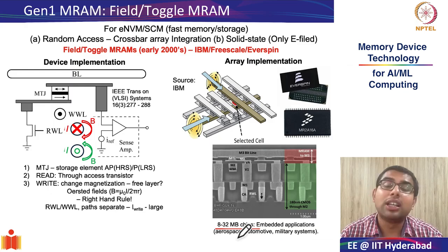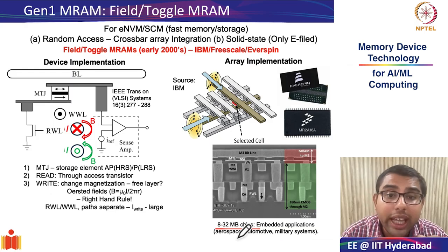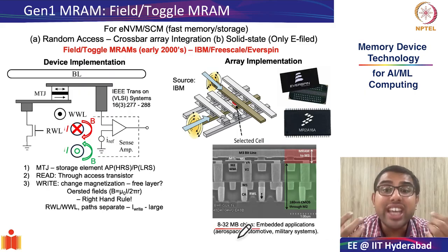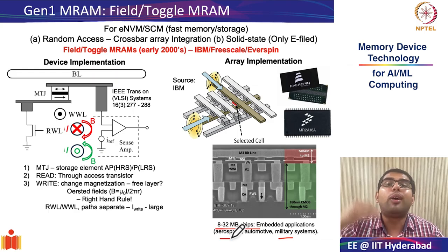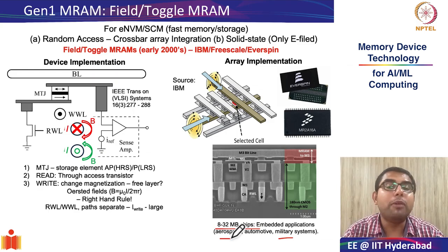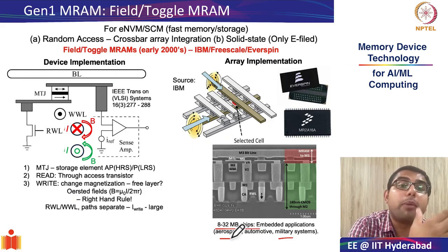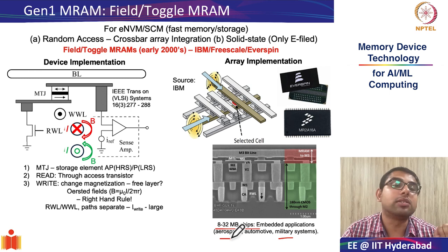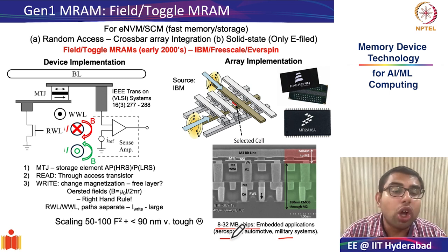This is because spin based storage and logic is generally immune to radiation effects, and that is why military and aerospace systems which are exposed to outer surfaces of space generally prefer spin based devices for better reliability as compared to charge based devices. However, the scaling of these toggle or field MRAMs was rather challenging.